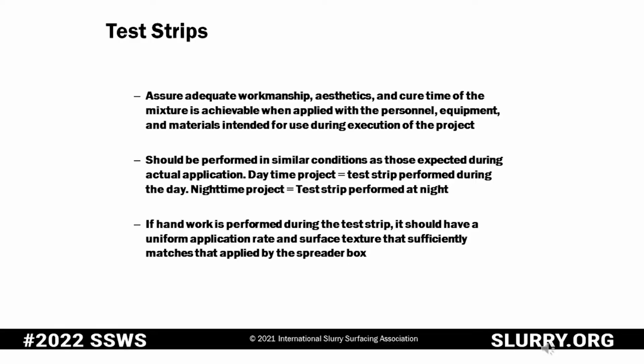So the reason we do them is to assure adequate workmanship, aesthetics, and cure time of the mixture is achievable when applied with the personnel, equipment, and materials intended for use during execution of the project. They should be performed in similar conditions as those expected during normal application. So if it's a daytime job, do the test strip during the day. If it's a nighttime job, do the test strip at night.